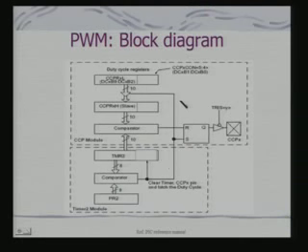So, if we go back to the previous slide, we can see what we are talking about. We are talking about setting the duty cycle, and setting PR2 for determining the period, and what we have not shown are the prescalers. So, we have to set the prescaler to get the PWM waveform. Once we set it up, we get the PWM in the correct form.